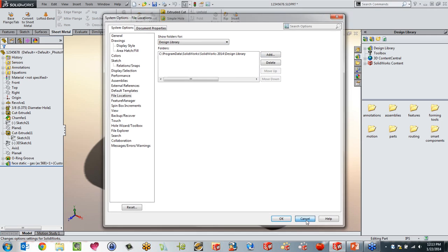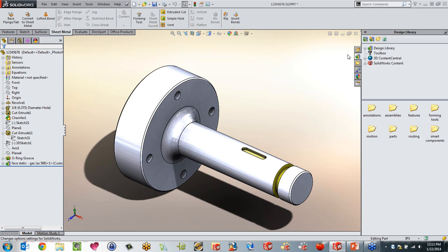So this might be where you want to change it. But it's all... I mean, I think it's awesome that SolidWorks have decided to give us all these existing features. But I might want to generalize and make my own design library for my own company. How does that work? Well, there are some different buttons up here, and one of them is called Add File Location.